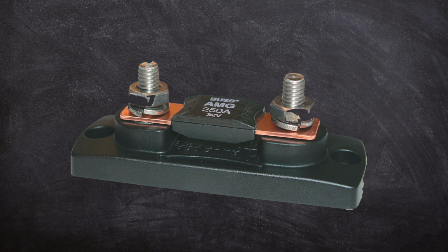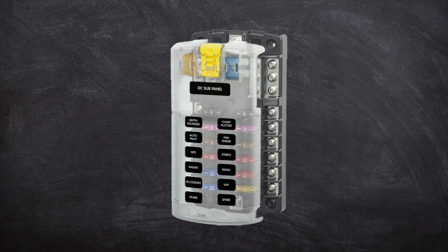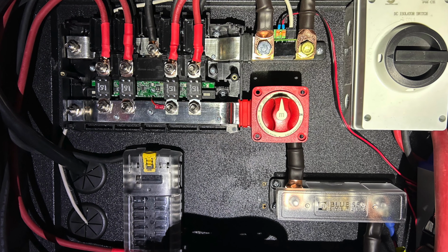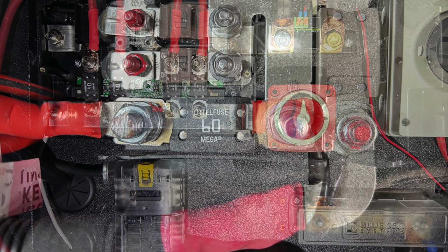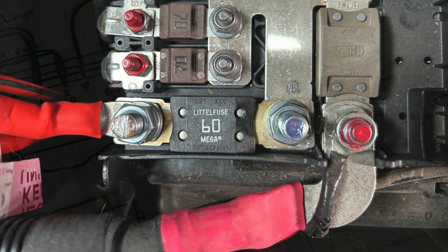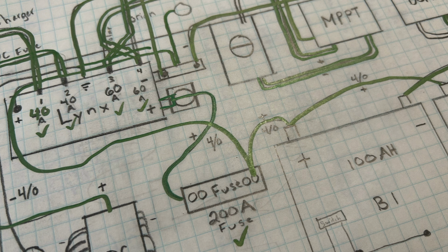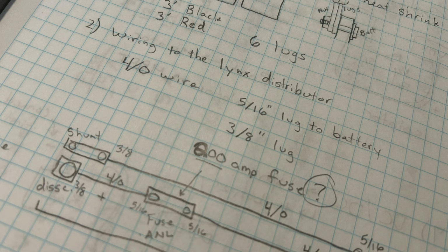Your best defense once a short occurs will be to have a properly sized fuse in place. Fuses protect wires and must be placed as close to the source of power as possible. Try to connect the fuse directly to the source's bus bar or within inches of batteries. Fuses must be sized properly to allow the needed current to flow while preventing excess current during a short. Each fuse must be sized according to your devices and power supply.